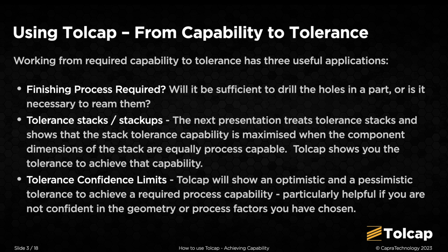Our next video addresses tolerance stacks, or stack-ups if you will. And it turns out that a good strategy to maximize capability of the stack, or to minimize stack tolerance capably, is to specify the tolerances for the stack elements for equal process capability. And Tolcap shows you the tolerances to achieve that.